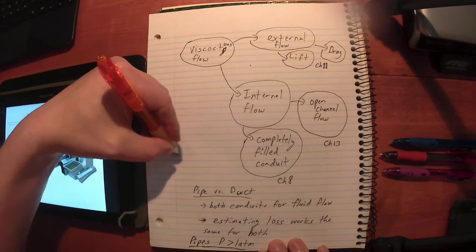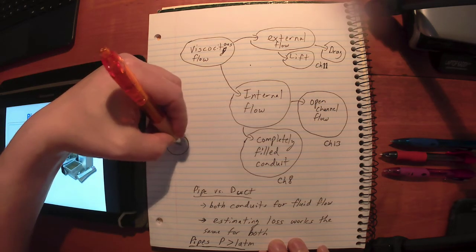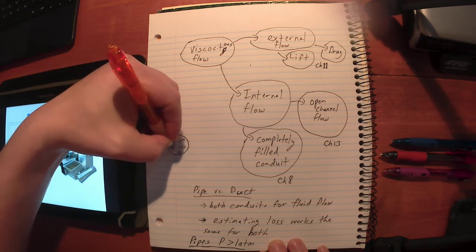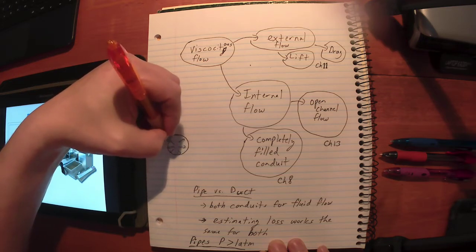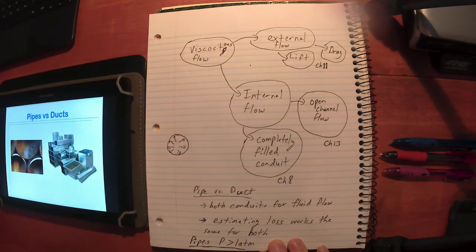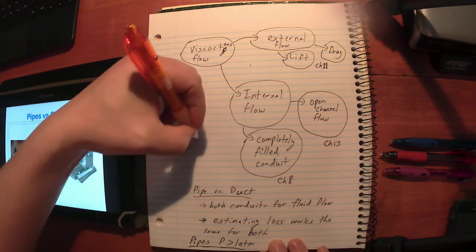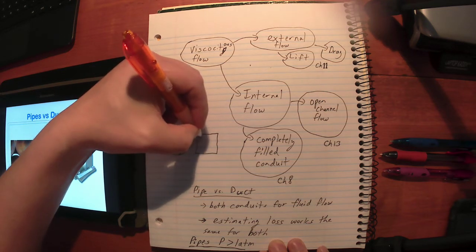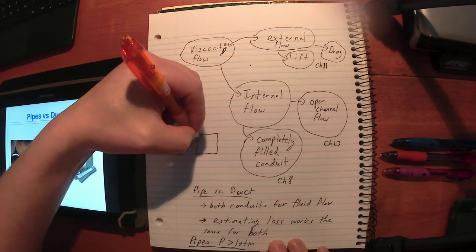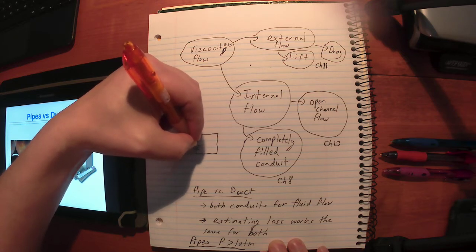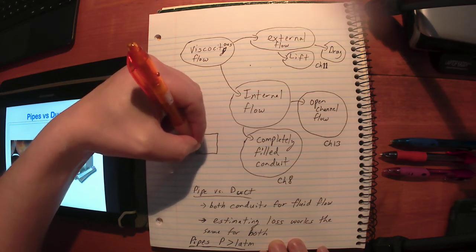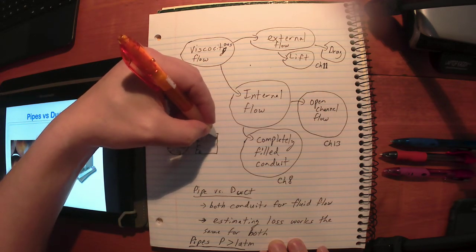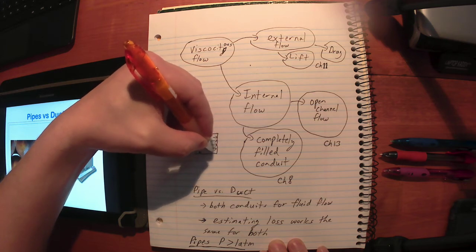If I'm looking down a pipe here, notice that the pressure is pointing out in all directions, and if I have a lot of pressure inside, it's pointing out in all directions, as opposed to another shape conduit where maybe I've got pressure pushing here and here and here, some sort of a square conduit, right? So again, pressure is going to push normal on all surfaces.